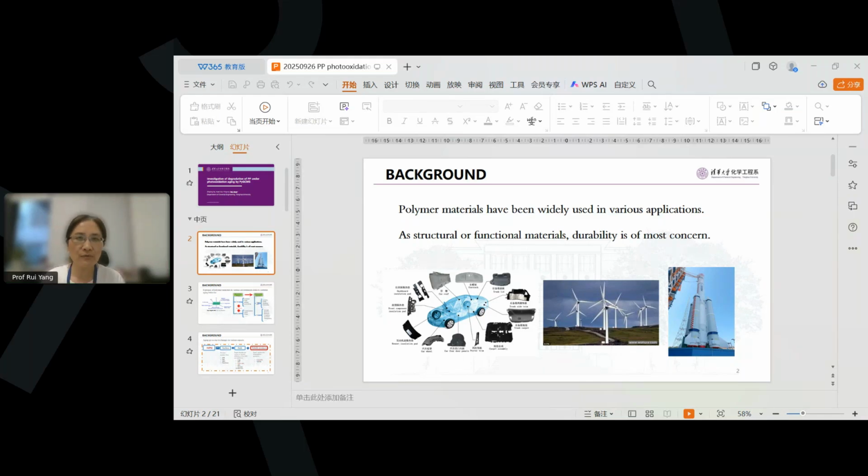During the exposure of polymer materials to environments, various kinds of changes happen. First are the macroscopic changes, including chemical or physical ones. About the chemical ones, you'll find oxidation, chain scission, cross-linking, etc. About the physical ones, you can find changes in crystallization, relaxation or creep, etc.